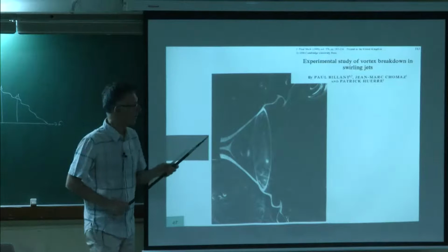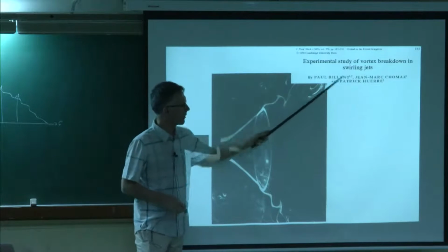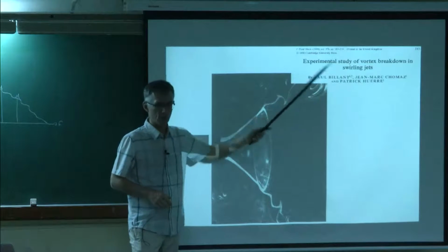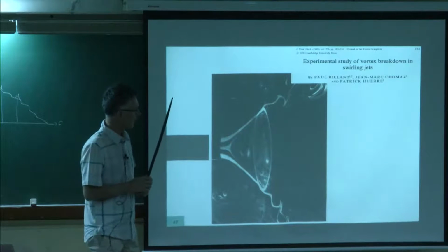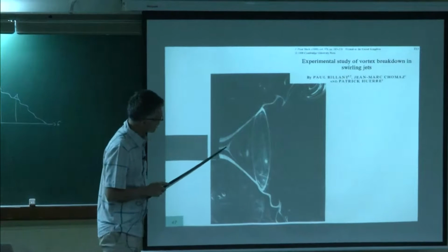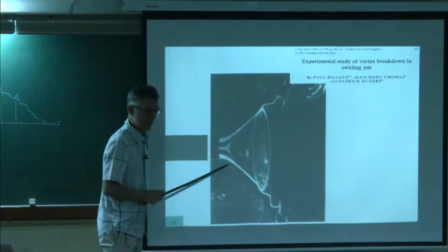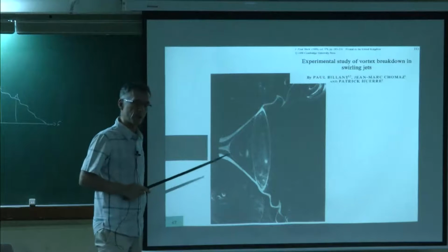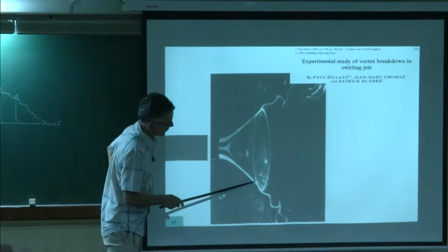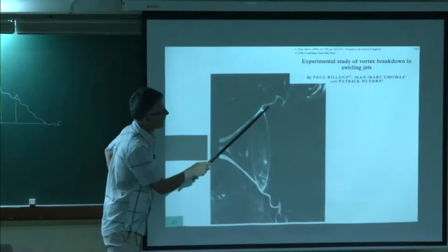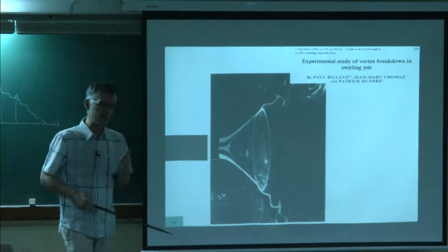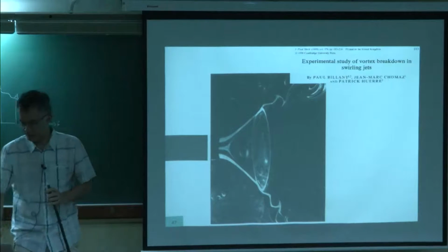There's no flame here, by this group here in Paris. Patrick Huerre was the guy who was first at USC, California. And you can see actually the huge bubble which is created. And by the way, you see also something else, that these flows have instabilities. And you're going to see that these instabilities, we'll have to deal with them at some point.